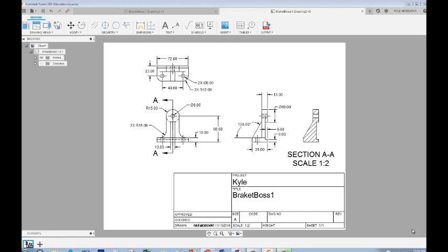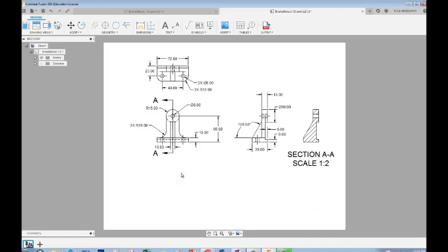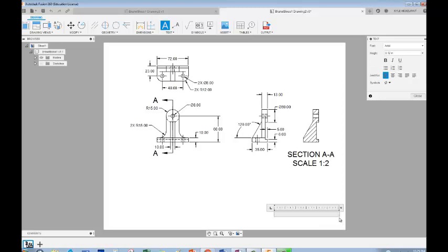So let's go ahead and click on the title block, and then all you have to do to delete it is hit the delete button and it's gone. And then to add some text, just go to this text function at the top, and you can see when you hover over the sheet you have specify first corner indicated next to your arrow. Just go ahead and click, and then click again, just about like that, and we can type our text in here.